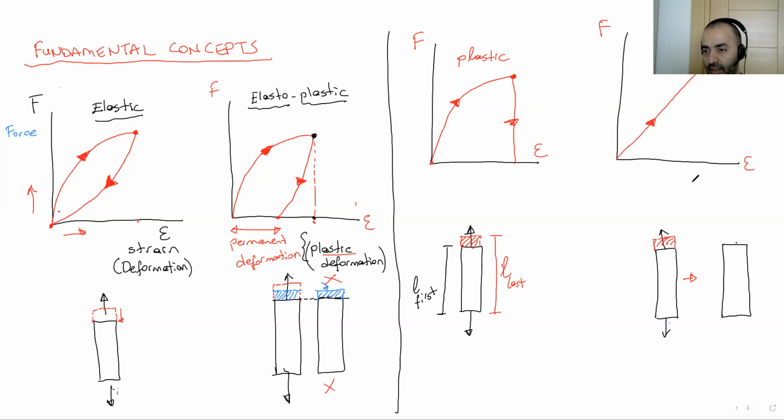My force increases, deformation increases. After this point, I reduce the force, and in this linear path, the deformation goes back to the initial position. So when I get zero force, I have zero deformation. There is no plastic deformation on this member. This behavior is almost similar to the first one, elastic behavior, but it works on a line.